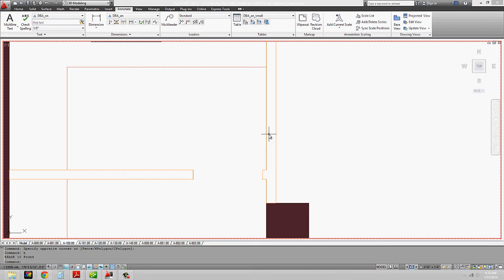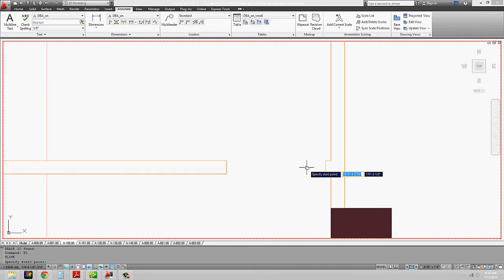So to draw a door, what I do is I draw a polyline, so I type in PL for polyline, and then I use my snaps, okay, and then this week we'll get into using our snaps a little bit more with the object snap settings below. But what I'm going to do is on the hinge side, okay, I'm going to click on my endpoint, and this is my door opening, okay. These areas here are the walls, okay, and this is a column in a project that I'm working on.